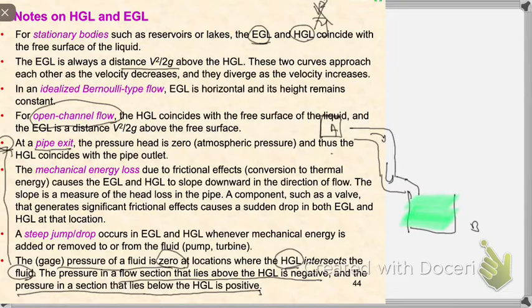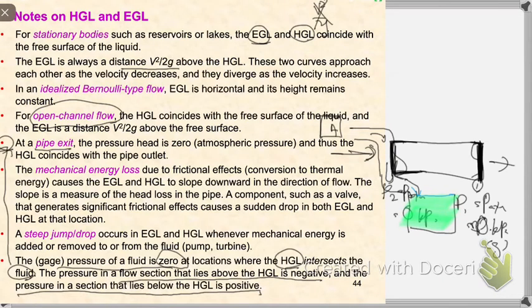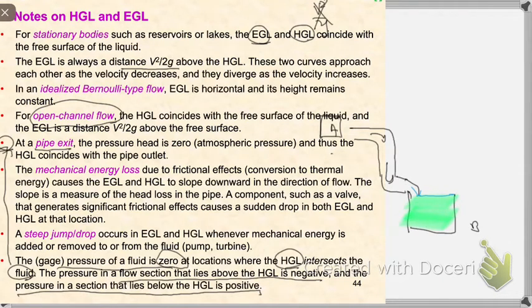So what happened is your water hits the water surface, and the pressure on top of the water surface is equal to 0 or maybe negative kilopascal depending on your atmospheric pressure. But down there, that is your HGL. Down there, your fluid pressure is a positive pressure.